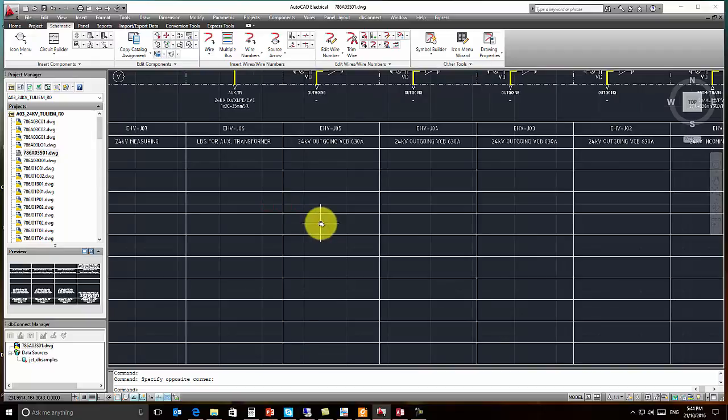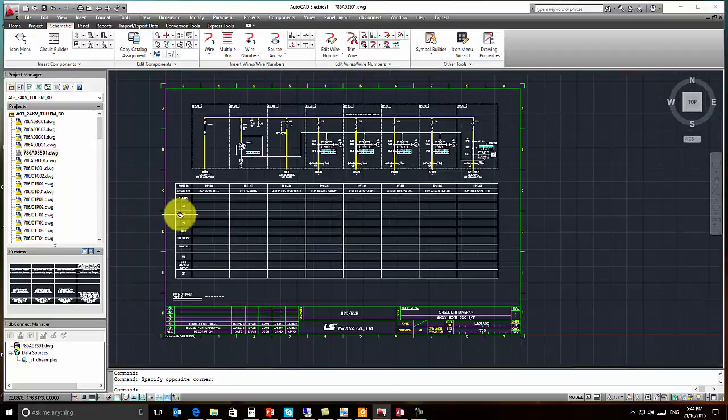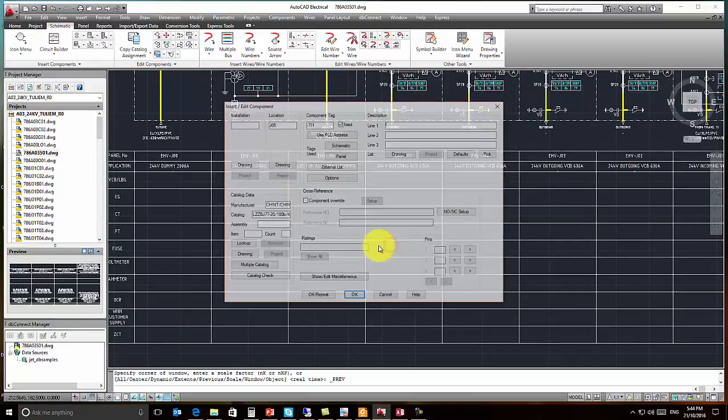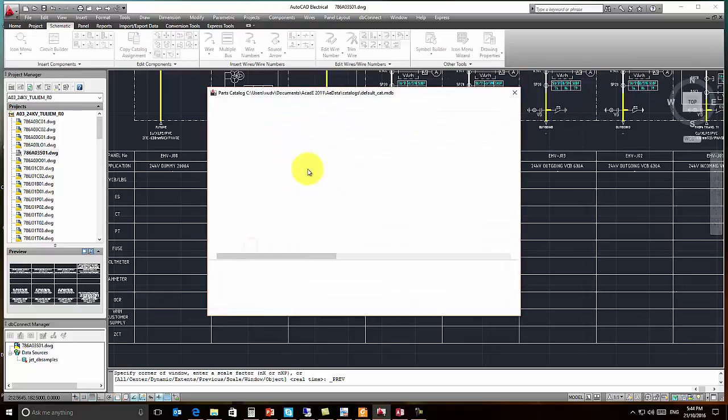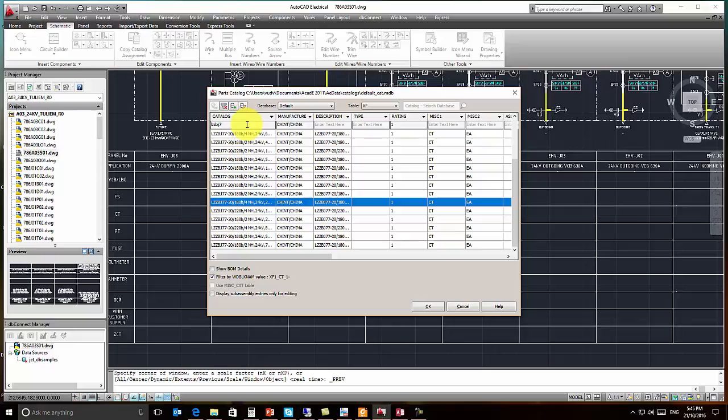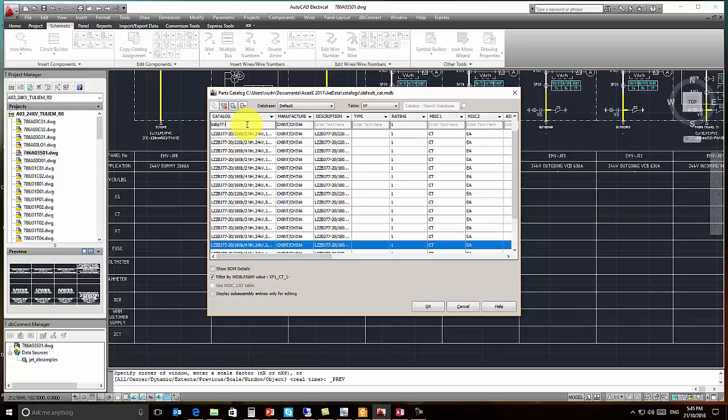I'm just checking, it's just left, not top left. I am going to go middle left, and you'll see why in a second. My height is 0.094. Rotation is 0. And I'm going to put my little tag right there. I'm going to hit enter.